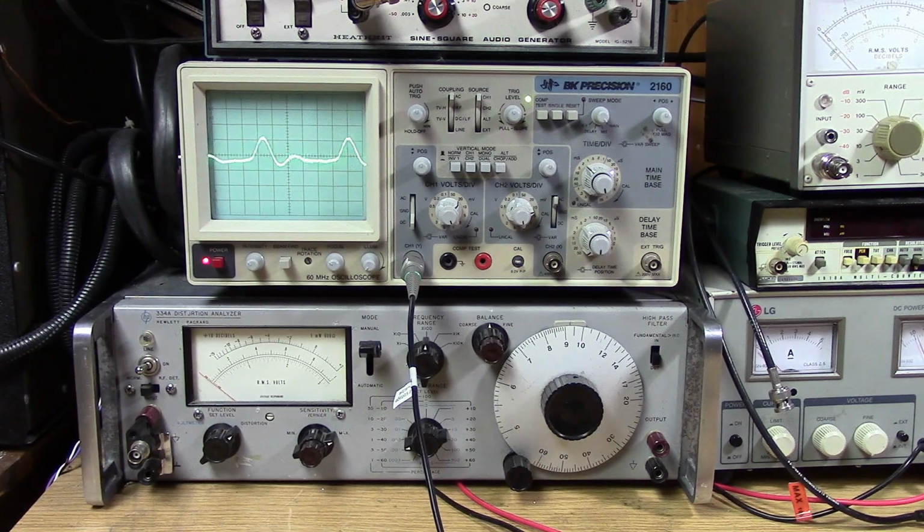So let's look at the waveform with the clipper in line. 1, 2. At low level it's very linear. But once you start talking, you can see lots of upward, hello, hello, hello. But the lows are attenuated. The low excursions are attenuated. Hello, hello, hello, lots of upward. But the lows are truncated in such a way that it's not sharp, but you can see it's compressed.